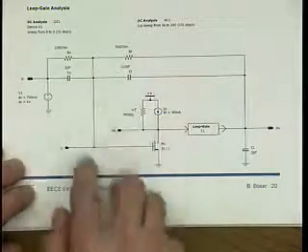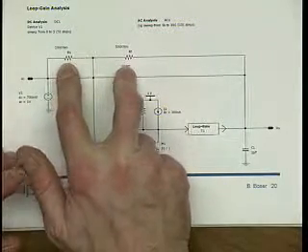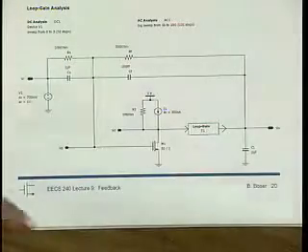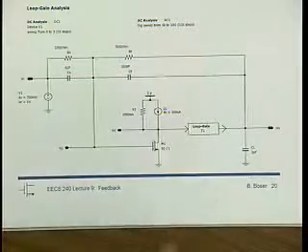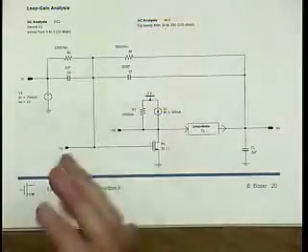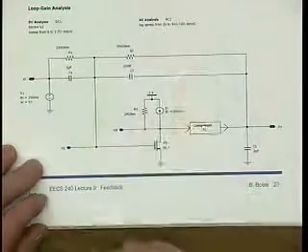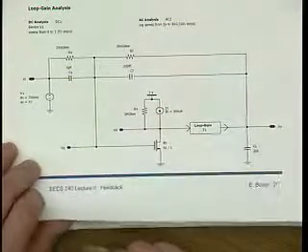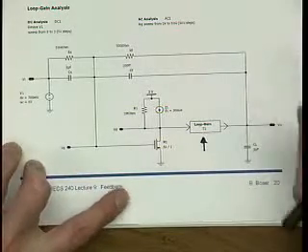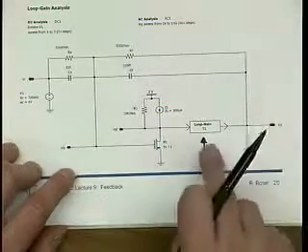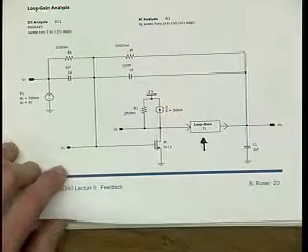In order to bias this point here, I just use incredibly large resistors again. Otherwise, I would need all of these switches and initial conditions on capacitors and so on. That's another good approach. You use whatever you like. I just find this usually the easiest, although my amplifier now becomes, of course, AC coupled. Okay, so I also found the point where I want to break my feedback loop. That's a fine point. I could have broken it here also. Would have worked too.